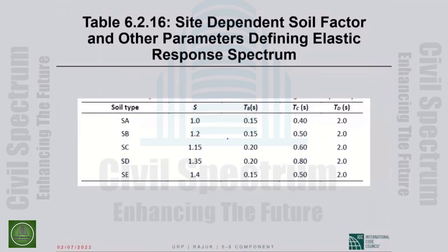Okay, this very important table in BNBC 6.2.16 gives you basically your ability to construct the design spectrum, site-dependent soil factor, and other parameters defining the elastic response spectrum.